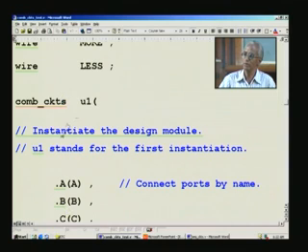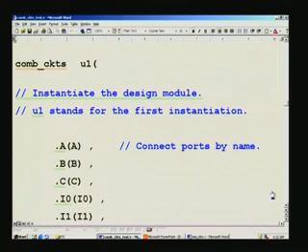Now, once you call this one, and there are IOs here, we have to list these IOs, and how do you express them? We will see that also, which is a new thing we have to see here. And before that, let us see why we should declare that output as a wire, right.